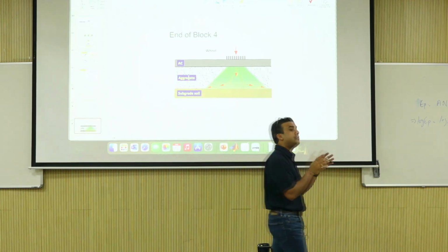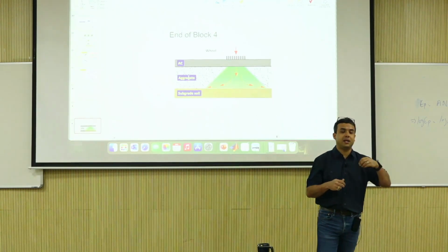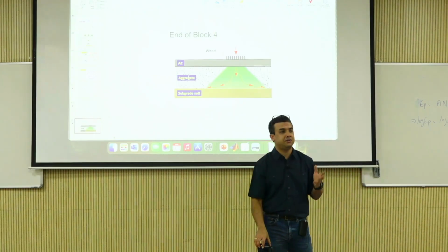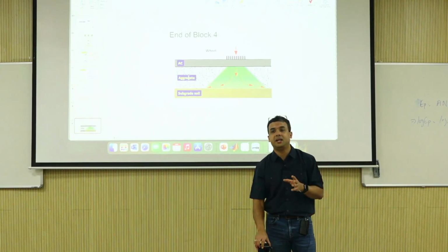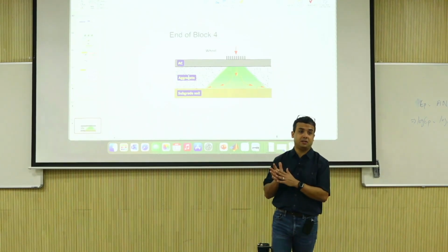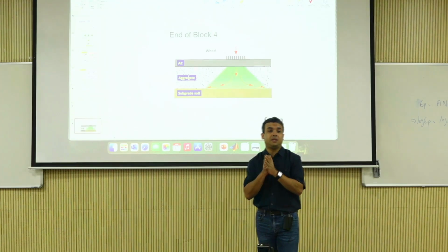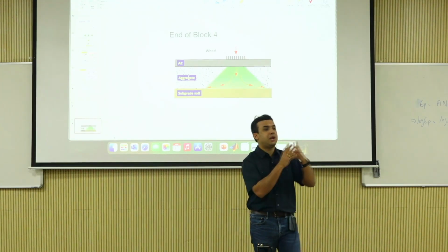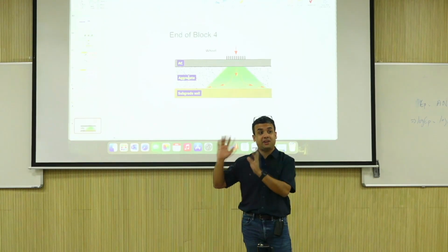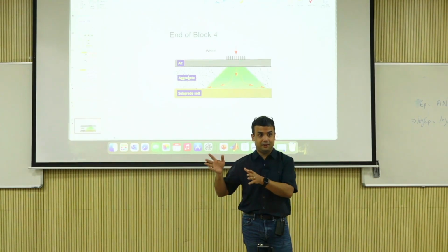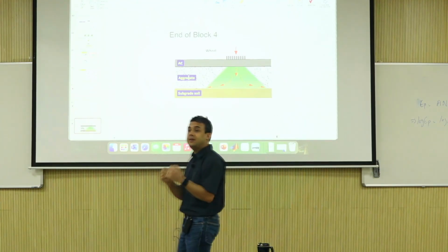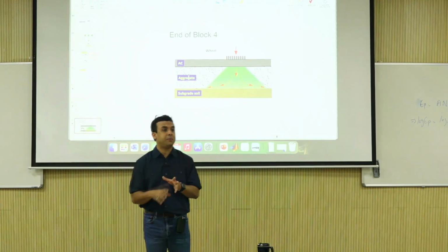The resilient modulus is recoverable, so you can predict it from different properties. It is stress dependent, is material dependent, yes, and whatever. But the plastic deformation is not something that you should only look at elastic response to predict. You should look at strength to do that. So your strength of the material is very, very important when you look at permanent deformation.